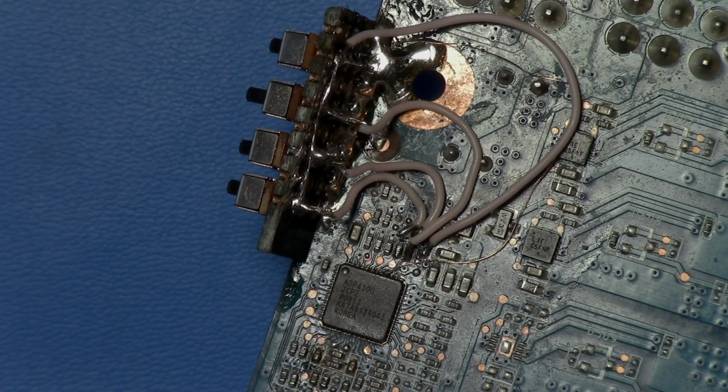But yeah, a lot of it is just once you figure it out, like I showed here, like, oh, this side connects to ground of these resistors. These ones are probably GPIO pins. Once you figure that out, it's pretty straightforward to just desolder the stuff you need to, add in your own switches, and call it good.